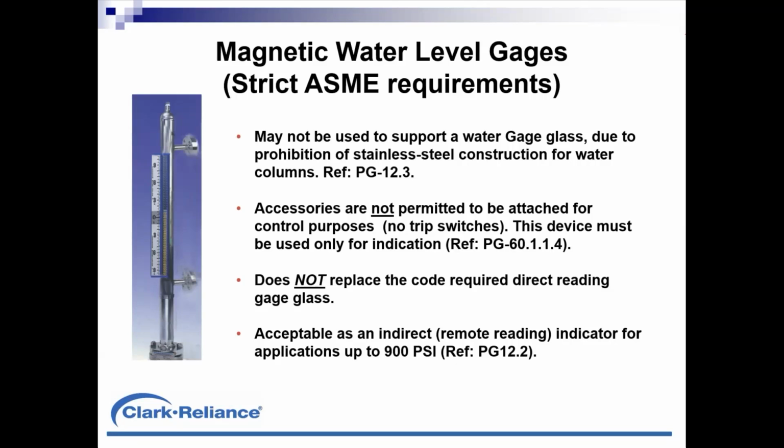If you see the float comes out perfectly clean, then that's a great clean water application. However, if you remove the float and there's a lot of debris or particulate collected on the upper end of the float, it can cause the float to either get lodged, or sink because it's become heavier. And in that scenario, you'll learn that in your particular application, that float may need more periodic inspection.